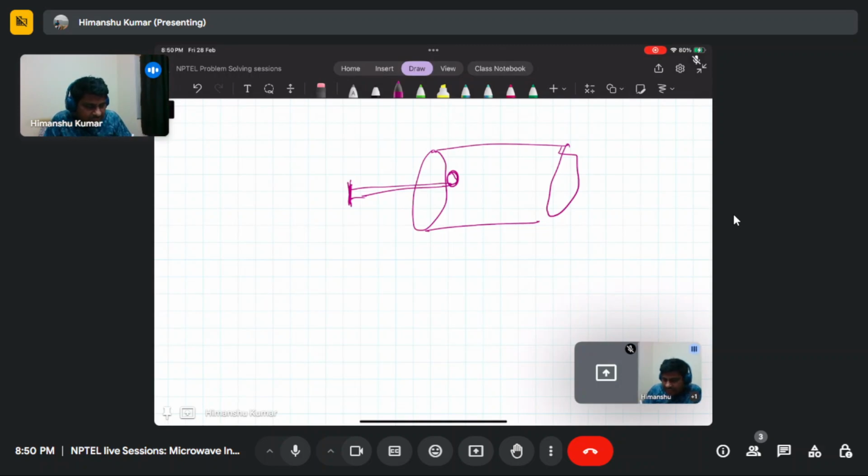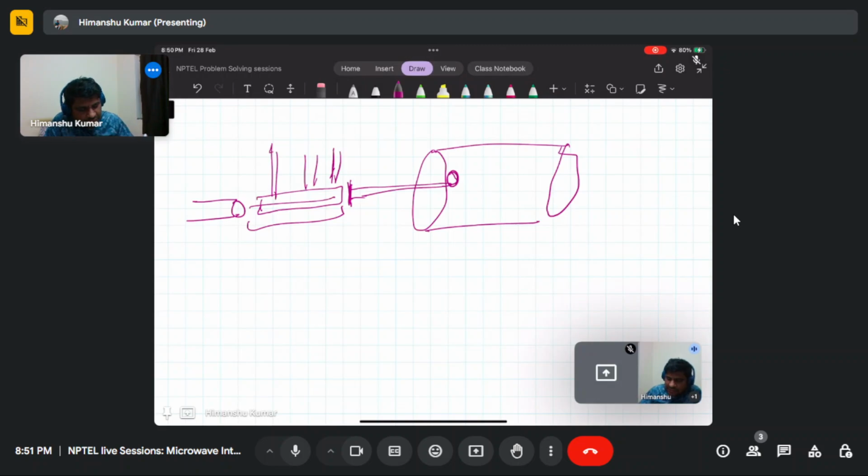And I have the coaxial line, which is a 50 ohm line, right? To match this, I use a series stub tuner, and in between these three shorted stubs are there. Because this is a waveguide, shorted parallel stubs can be used. I connect this whole stub tuner assembly in series with the coaxial line, but within this there are parallel shorted stubs.